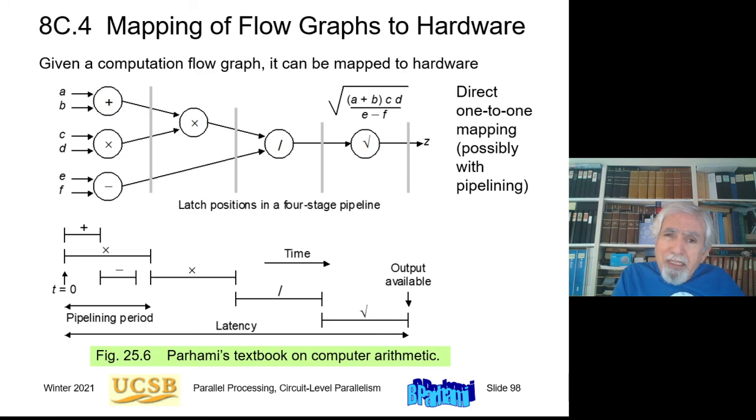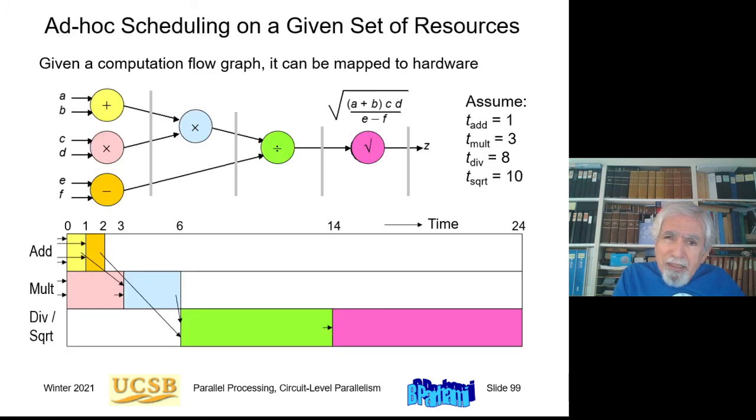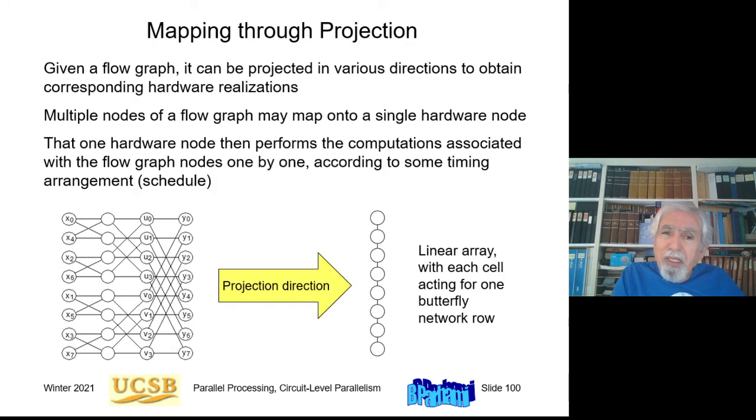Okay, I'm going to skip this and go directly to, now if you're doing a 1024-point FFT, this circuit for 8 inputs has 3 columns. Remember that this leftmost column is not really any hardware. These are just inputs coming in.